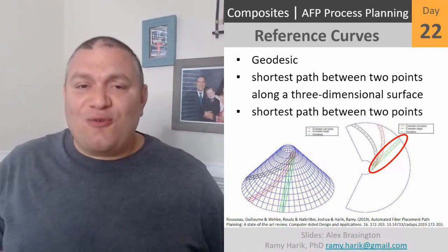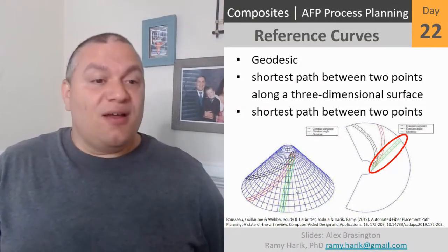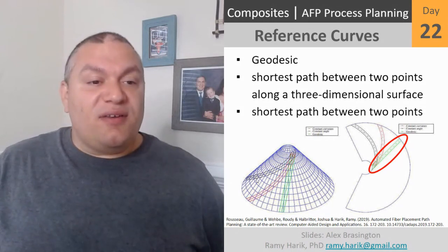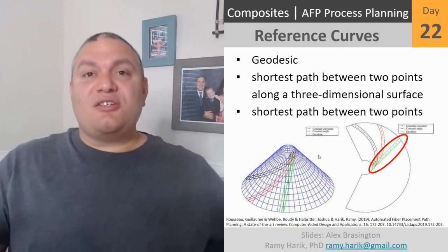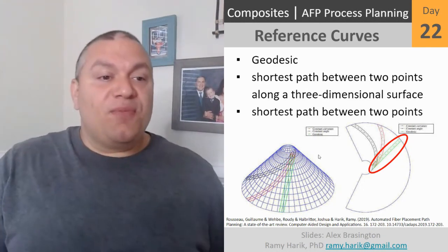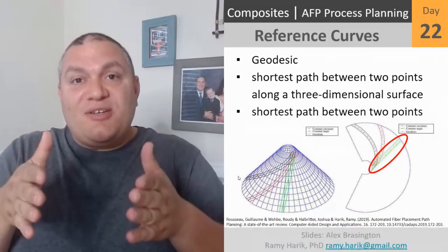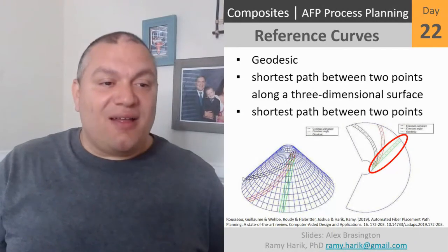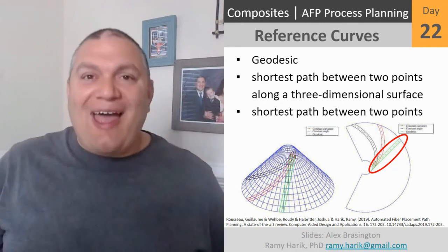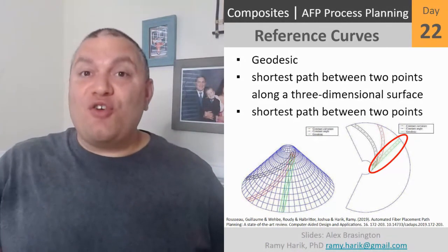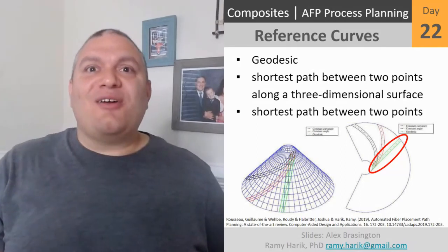If you're still lost and confused, take a look at this graph, and let's explain it once again. So this is your constant angle. You see the black curve in here. This is the cone that you wanted to cover. And if you have done the constant angle, as the machine moves, the fiber is still at its constant angle, you would have this curve. This curve will not have angle deviations and you will have your design of 45 degrees, however, it will have a lot of steering.